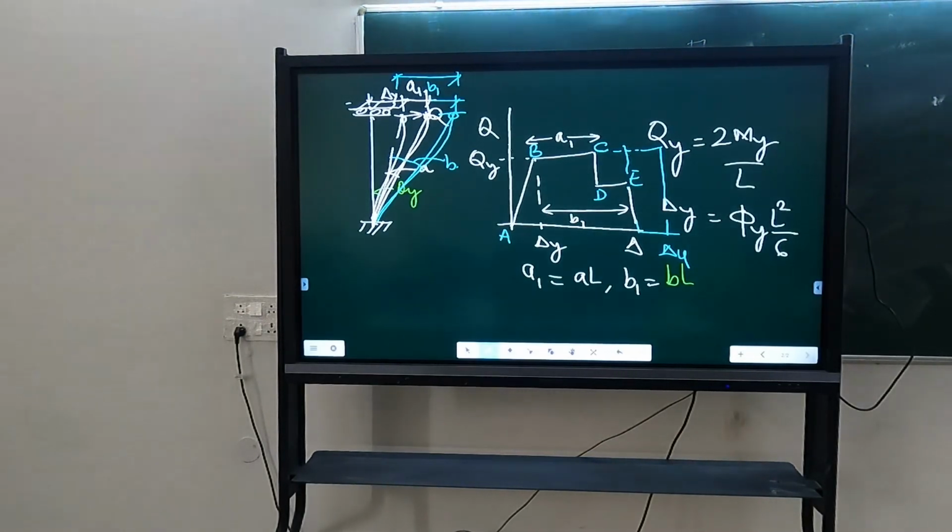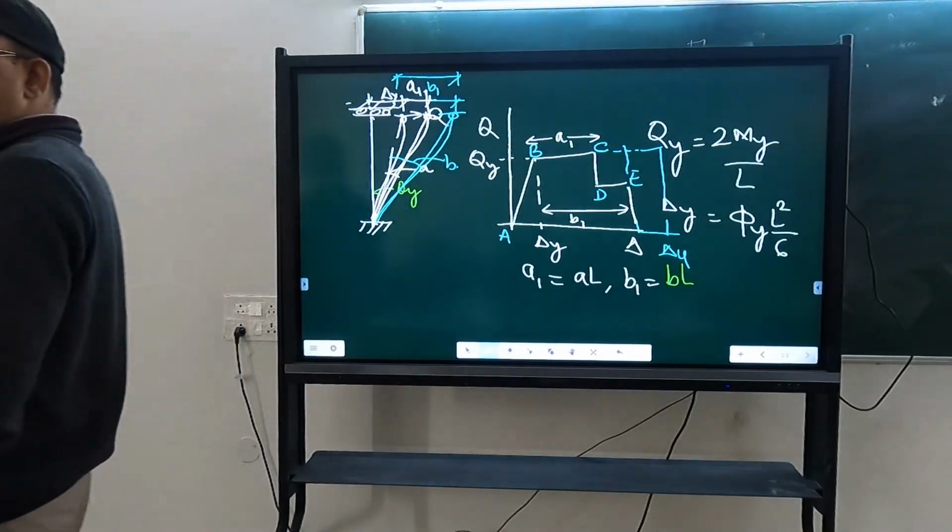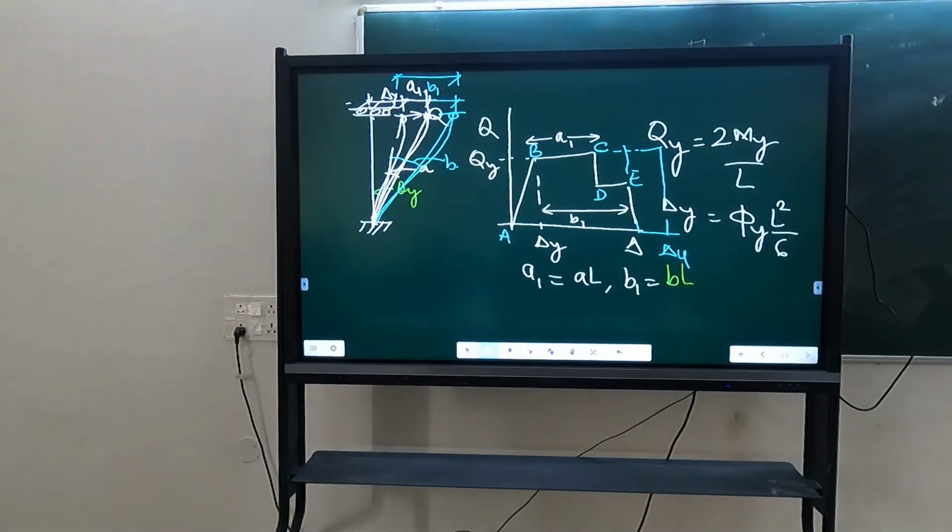Because the failure point due to low cycle fatigue has also come closer. The curvature at which we are getting failure under monotonic loading is longer. When you subject it to cyclic loading, it will converge, it will reduce, it will fail much earlier, because steel is going to fail at lower strain now.